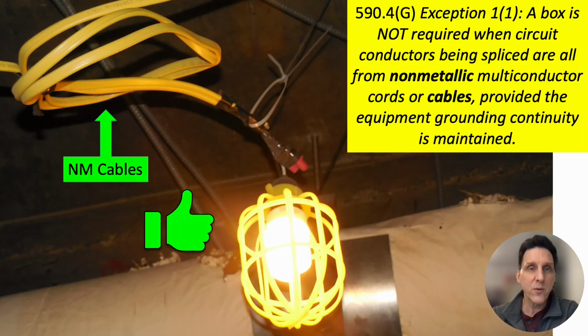Now let's take a look at another one. This is some NM cables being spliced. Very common to use NM cables for temporary power because it's relatively inexpensive, and you can use a lot of it, and it's easy to install, right? So we see the 2 NM cables being spliced there. No box needed, not required.